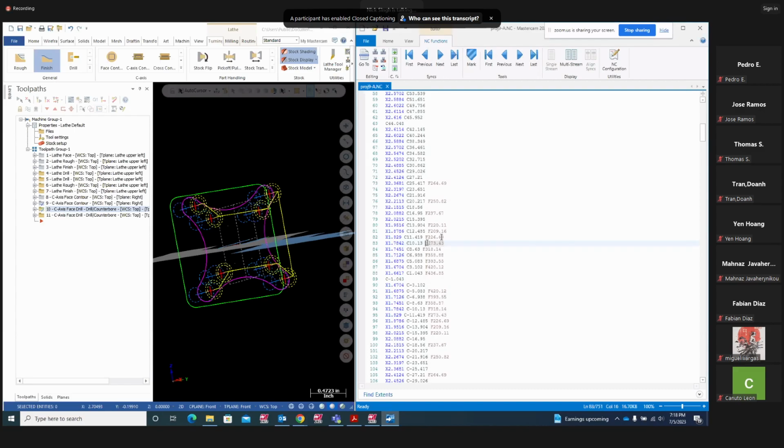And it controls the feed rate, where it's going to go at an arc or spindle speed. It's going to change. It's going to control the feed rate by itself every step. So look at this here, 21.916, 23.6. Look at the increment. It's not even 1 degree each time. So the combination of X and C axis is going to create that shape of your part. And again, you can only do that on a lathe machine which has C axis capability. Not every machine has that.